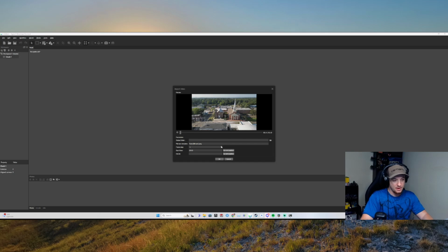What we're going to do here is set the frame step. What it's basically going to do is take your video and chop it into a frame per second if you leave it default. So if you're filming at 60 frames per second, it's going to chop you 60 photos per second, and it can give you a pretty highly detailed model. For time and simplicity's sake, we're just going to set the frame step to small. It's going to make it so it's fewer than 60 frames per second and cut down on storage and speed everything up for us.